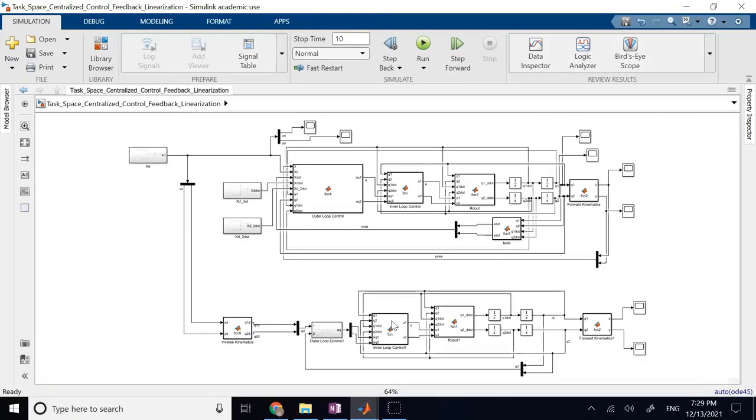and that makes your bottom method a little bit harder to work with than the top one, which directly works in the task space, and it never needs you to calculate what? Inverse kinematics. Okay, because calculating, as I said, forward kinematics and Jacobian and so on, as long as you are using the DH method, is not so difficult. It's a very systematic approach. You follow the DH convention, you can always achieve forward kinematics, you can always get the Jacobian. But for inverse, there is no guarantee on that.